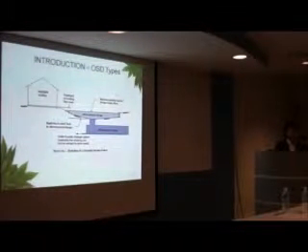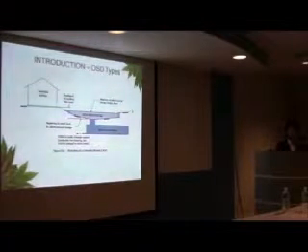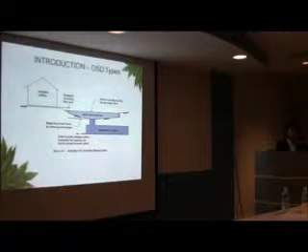This one is a composite storage OSD, above ground and below ground. Very simple. The water flows from the higher land area and then fills up the underground OSD. If there's a lot of water, the underground OSD will be full, and then the water will be stored above ground.